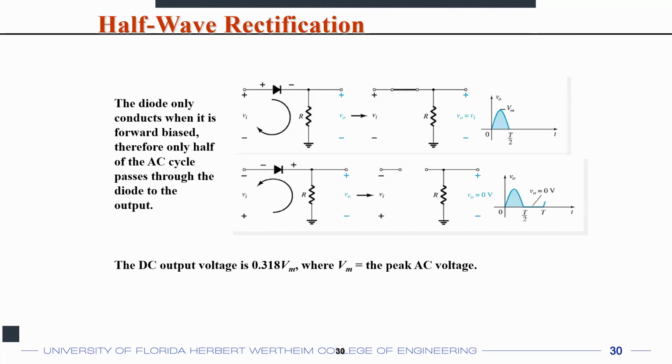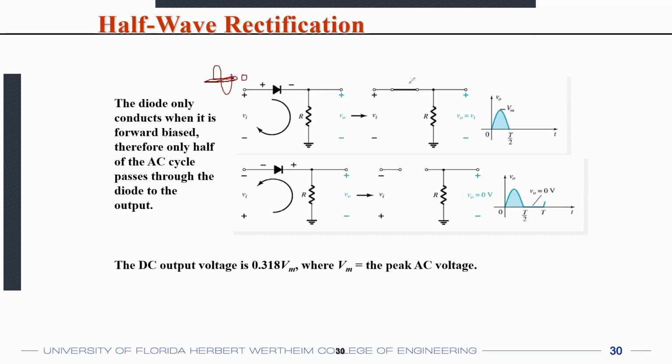So if you have an AC voltage or AC current, can you create a DC out of it? The answer is yes. And the solution to that is by using a half-wave rectifier, which is a diode-based circuit. You already know the diode only conducts in one direction, and you can use that property to make sure that if there is an AC sine wave at the input with an average value of 0, so let's say your average DC potential is 0, then on the output side, as the diode is shorted, as it is forward biased, you are interested only in the positive half cycle.